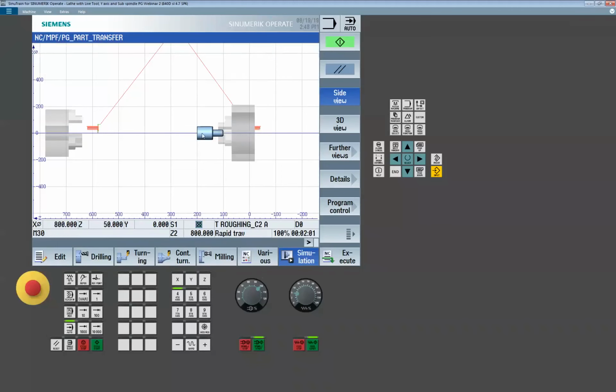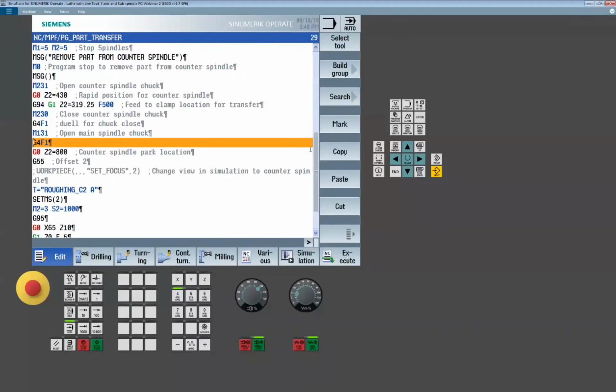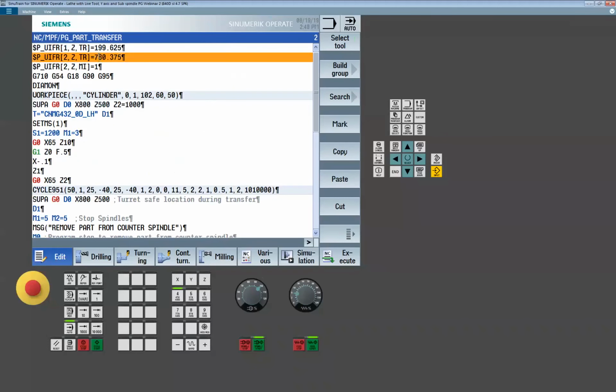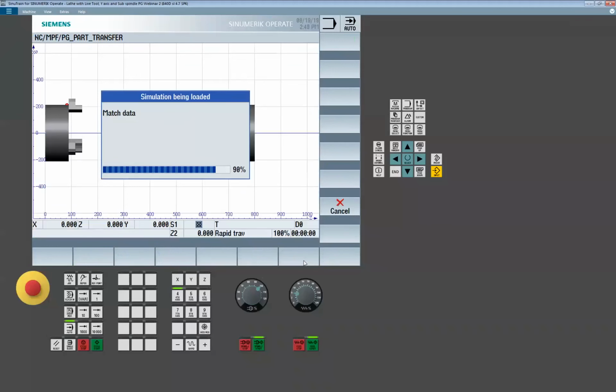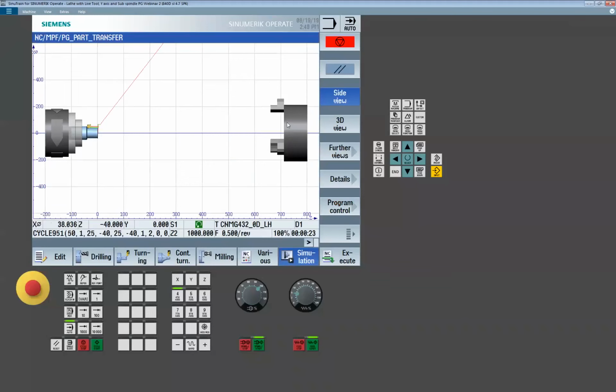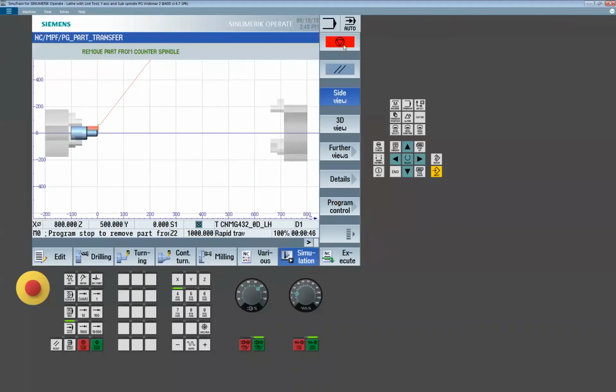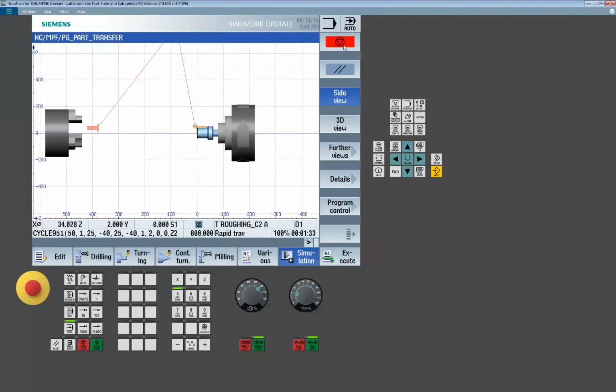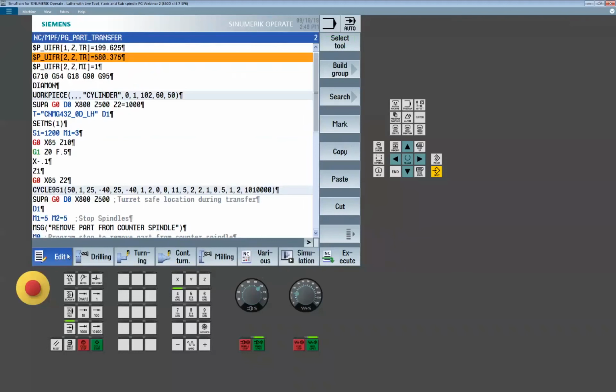Well, now I'd have to change that value right in the work coordinate system. That's a direct result of this work coordinate. So this is a relatively easy fix, but it gets a lot more complex quickly, depending on if I'm shifting the part around in the main spindle, or if I wanted a different throw to mount in the sub spindle. So working from either that spreadsheet I talked to you guys about, or just mapping it out and drawing it, is hugely beneficial when you start dealing with this type of technology. Okay, so hopefully this starts to give you a feel.